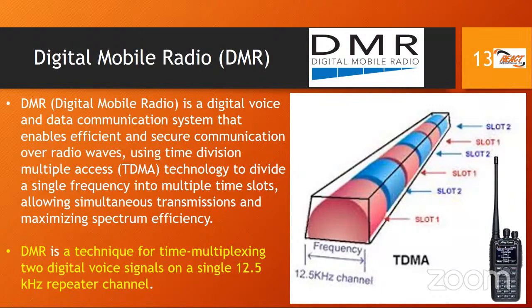Digital voice, where our voice starts off as analog, goes into a microphone, is picked up, and then we digitize it using an analog to digital converter. And then our voice is digitized using a vocoder, and that digital voice goes over the airwaves. So when we say digital mode, we have modes using a computer, yes, but we also have digital voice modes.